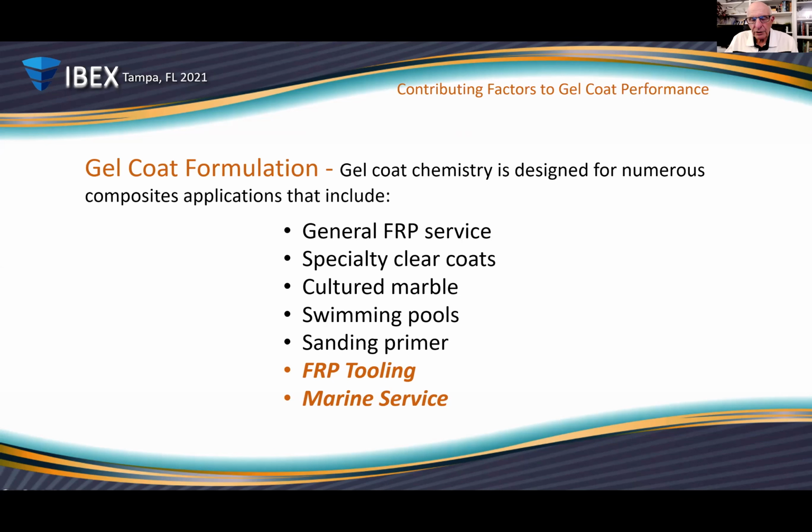The gel coat manufacturer is always wrestling with the specifications of the gel coat, in terms of everybody wants a glossy product. Consumers like to buy shiny things, and boats need to be shiny if they're going to sell at the boat show. So one way to make a gel coat highly glossy is to make it very hard, and then the gloss level is high. However, if the gel coat is too hard, it tends to crack easier than a softer gel coat. So if you want a gel coat with good durability, a gel coat that has toughness, then it may not have the same gloss as a hard gel coat.